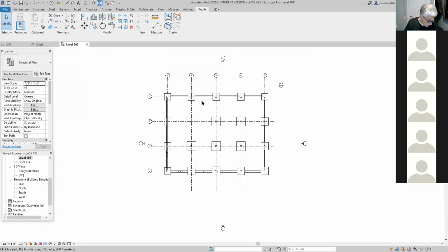And most of the information for that wall will be in elevation. You'll see that in elevation in section. Most of the information for where that wall opening is, is all in section DD. It tells you the wall opening is 3 feet by 7 feet. That's the size. It tells you that it's 1 foot 6 plus 8 inches. So in other words, it's 2 feet 2 inches below elevation 102. And it's centered right between 2 and 3. So you've got all the information there to put in the opening properly, okay?